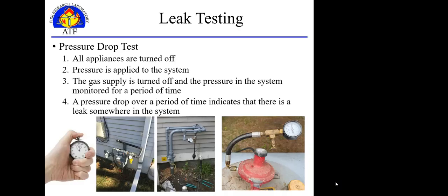Pressure drop is just like it sounds. I turn everything off, I apply pressure to the system, and I monitor that for a few minutes, and then I see, is there a leak or is there not a leak?